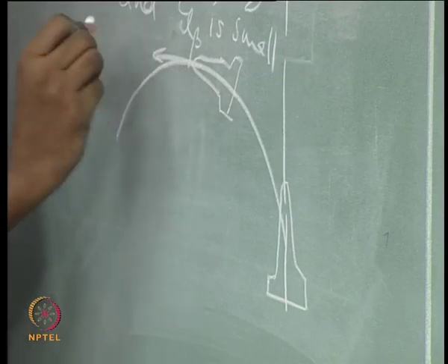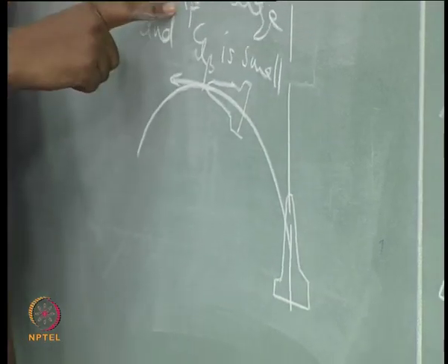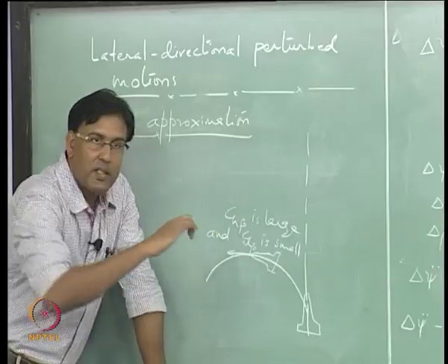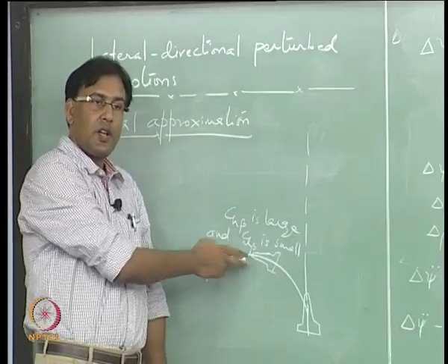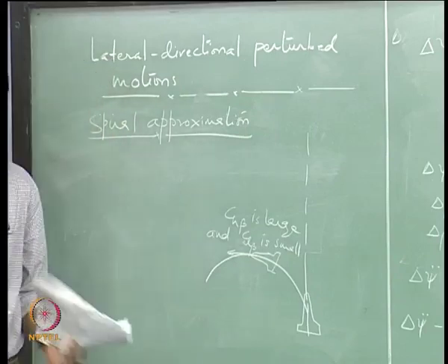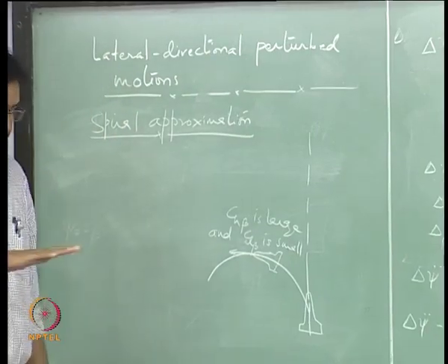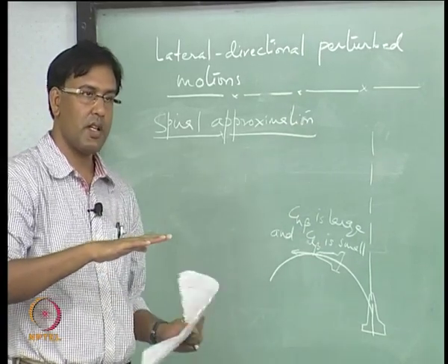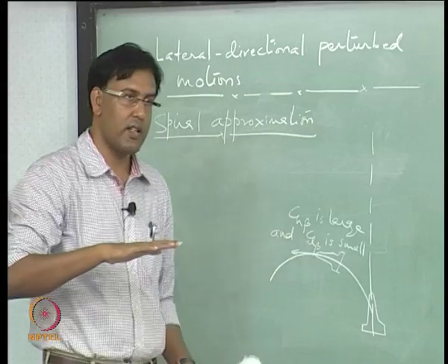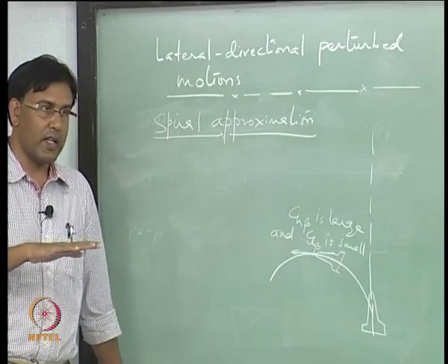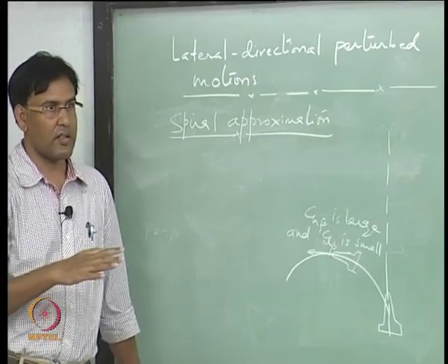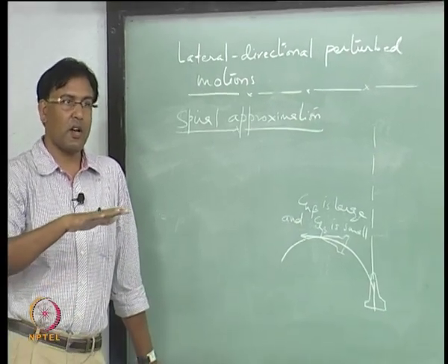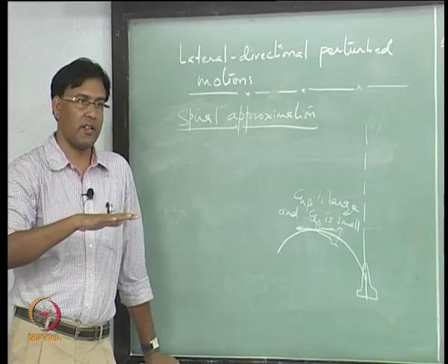So, beta is constantly being killed because of the Cn beta, right, large Cn beta. Roll is the aircraft is banking because of low Cl beta, right. So, it is like you are flying like this and there is a perturbation from side, side velocity, there is a beta introduced and then aircraft starts banking, and this banking is so slow there is not much change in the roll rate as such, okay.